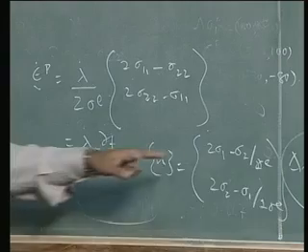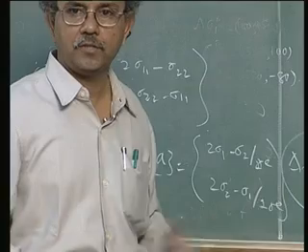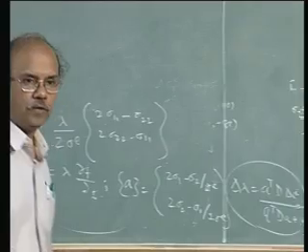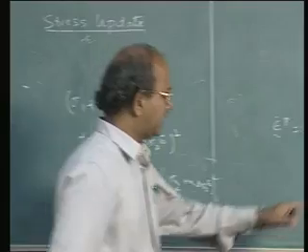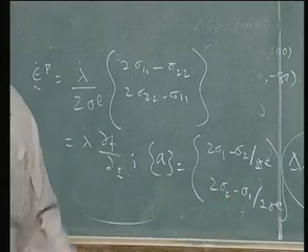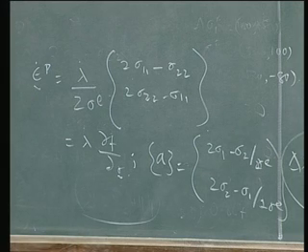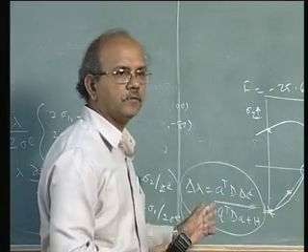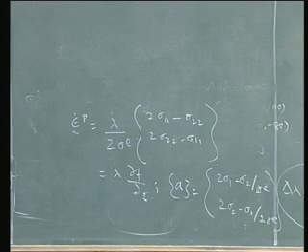What is this sigma E? The equivalent stress, which is sigma Y, and in this case happens to be 200, where it cuts the yield point. So that is the A. Please calculate what A is, and then substitute it into this expression and calculate delta lambda. It is very simple. What is 2 sigma 1?